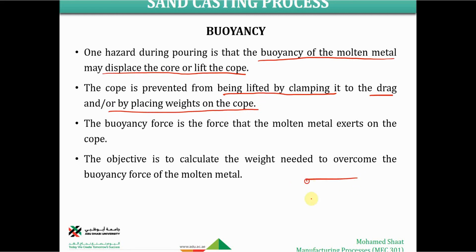As we said, even if you remember, this is the cube and this should be here, the drag, and this should be the cube. And in many of the cases, this is the flask, and there should be the mold cavity and the gating system and the riser, these other things of the sand mold. So in many of the cases, we could use these handles and add some bolts and nuts to clamp these two parts together against the buoyancy force.